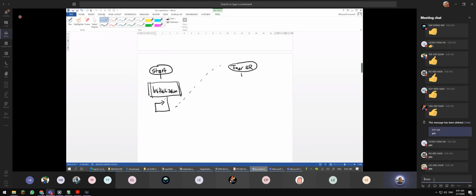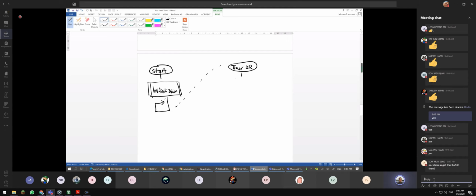So no matter what is going on, when an interrupt is happening, let's say after 1 millisecond, we need to reload the timer. And as you know, we need to clear the interrupt overflow, or clear the timer interrupt.